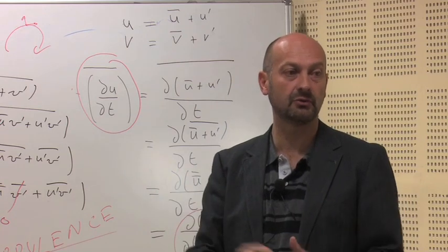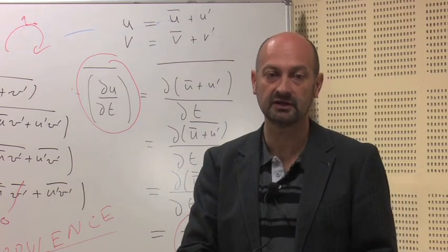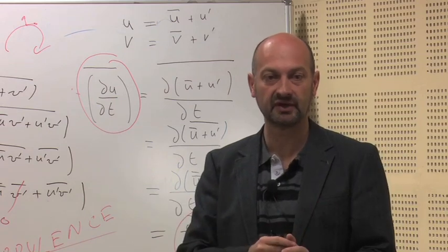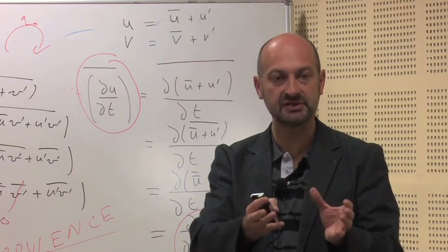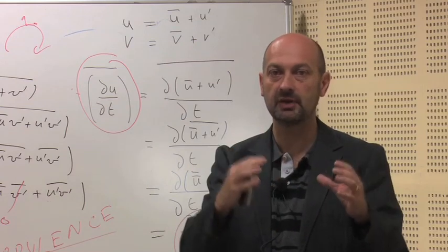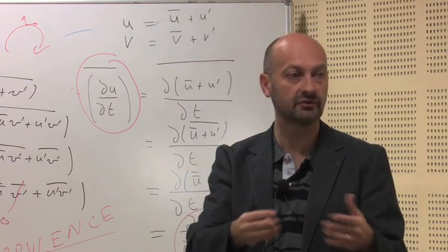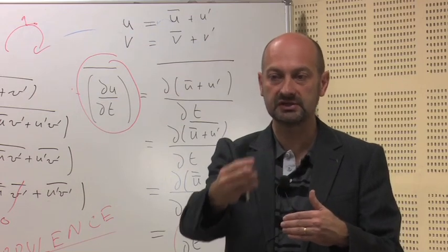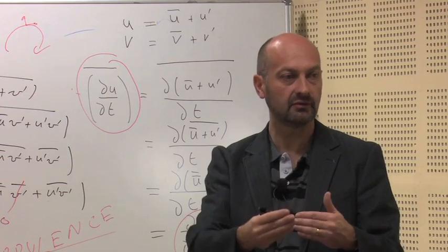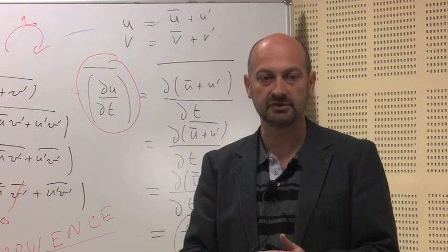So you have to be critical when you do that. But of course you have to validate, and there are many strategies of validation. There are, let's say, numerical strategies to see that your model is consistent. You change the mesh, you want to see mesh convergence, for example. You want to compare different models. When you increase the accuracy and you see that indeed you have convergence, and then you compare with experiments.